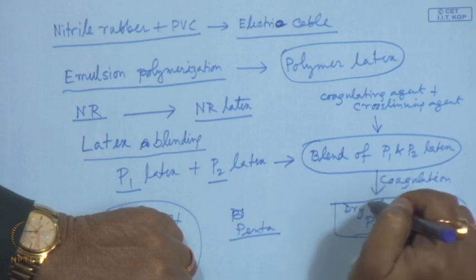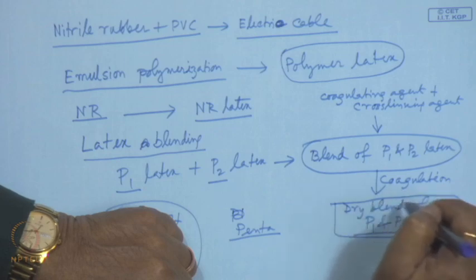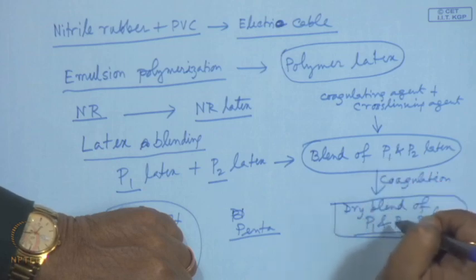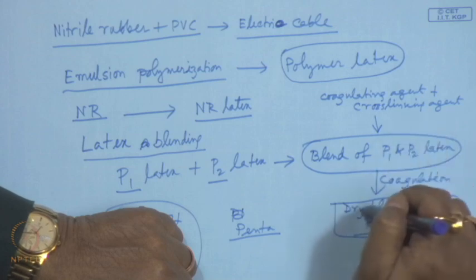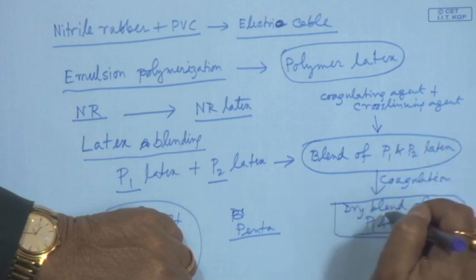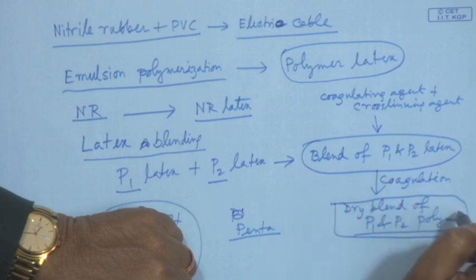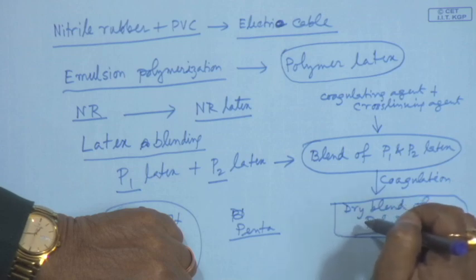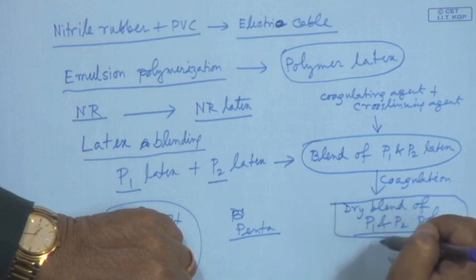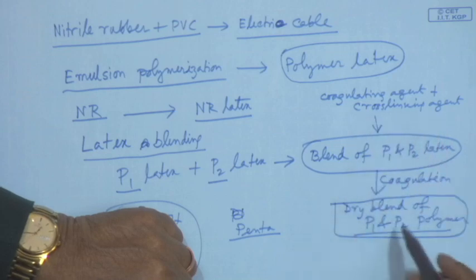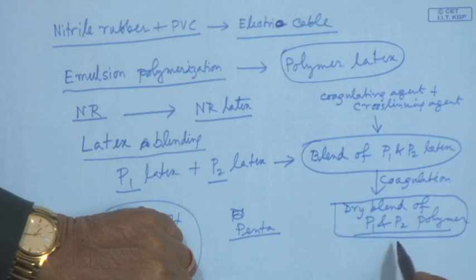After coagulation of the 2 component polymers along with this cross-linking agent, it is washed and purified, then it is given a shape and heated in an oven or in a mold, where during heating this cross-linking agent present in the coagulated polymer blend will decompose to form some active ingredients which will form a 3-dimensional network of the polymer chains.